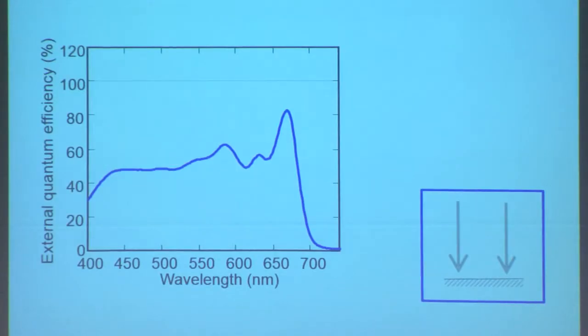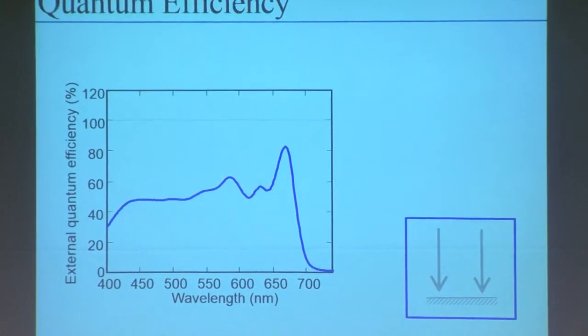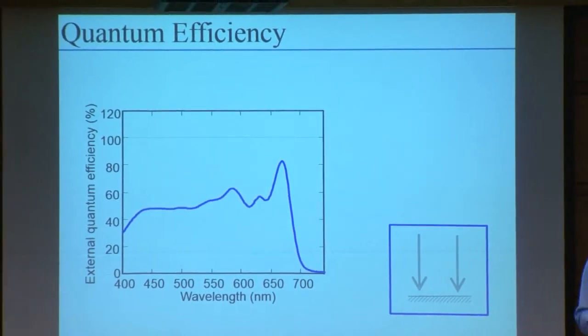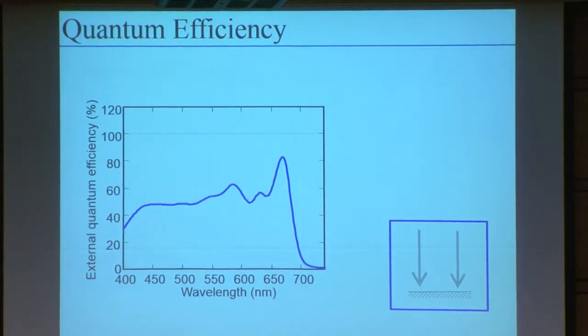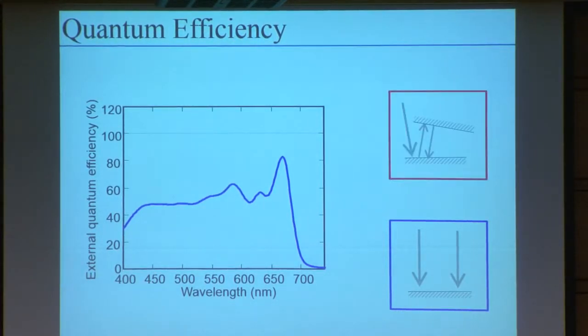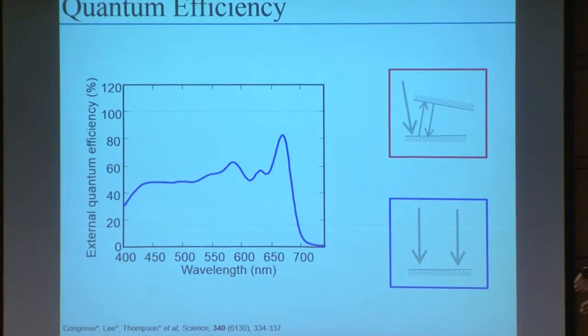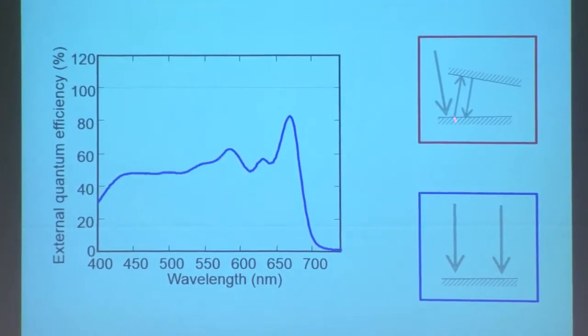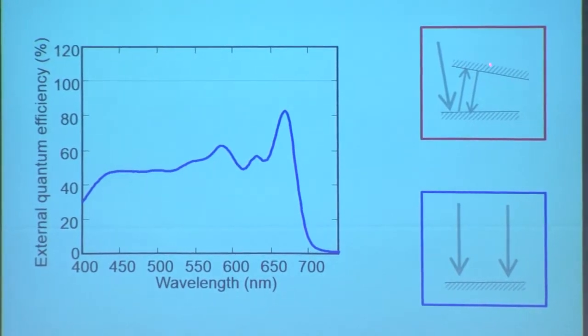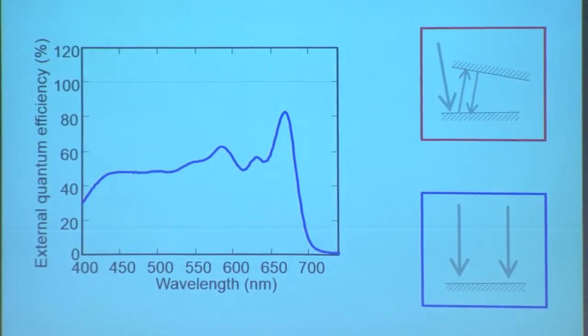But we weren't satisfied with doing an absorption model. Nobody likes to hang their hat on an IQE measurement. They're notorious for being fickle and having large error bars and all sorts of stuff. So we borrowed a supercontinuum laser from Vladimir Bulovic and put our solar cell in a light trapping scheme that looks like this. We brought our laser light in 10 degrees off incident, which then got 50% absorbed here in the device, and then captured the reflection with an external mirror and sent it right back into the device. And so this boosted our absorption to about 70 to 75%.